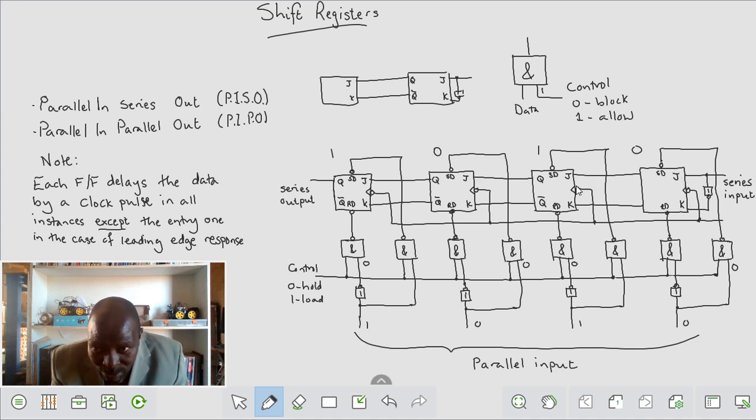So that also must be set to D-type. This one is easy. We didn't have to use an inverter, because these two, I neglected to put my Q and not Q there. They are already opposites and they're doing that job. So same as the other one. So they're all set as D-types. So this is basically how we would achieve parallel in. Okay, and our series output.